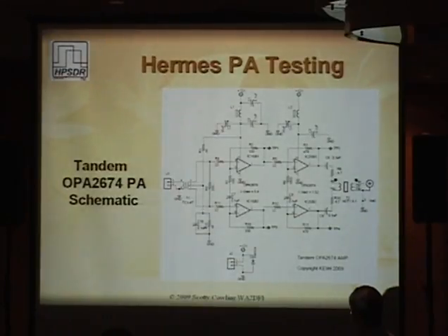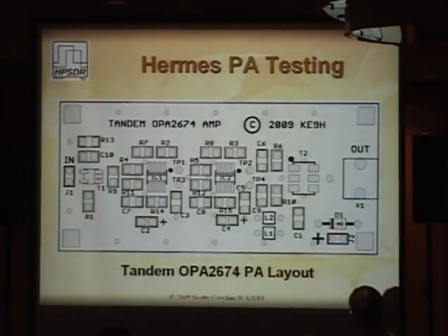Here's the schematic, very simple again. No big heat sinks for ½ watt. There's the top, the board layout. Graham did this. He tried to use large components so it's not too tedious or daunting to assemble. I think the worst part on here is the IC, and it's not bad. 50 thousandths pin spacing, there's 2 of them. Everything else is like 1206s or larger.